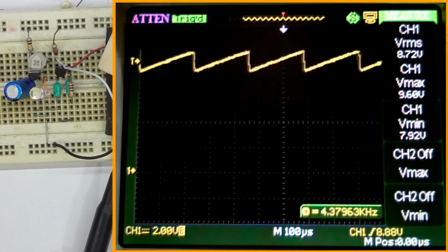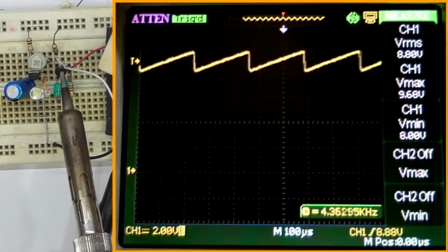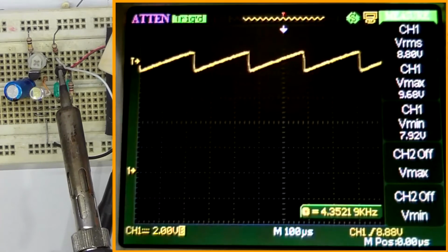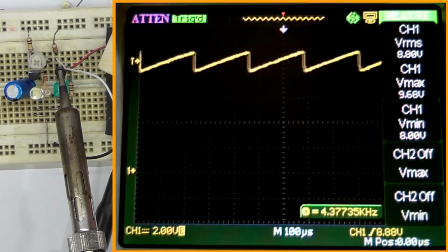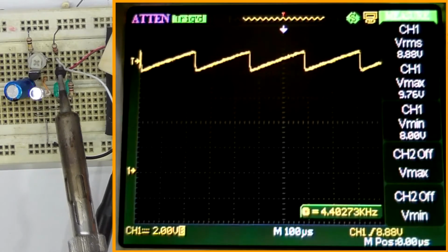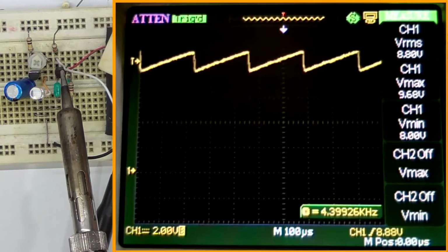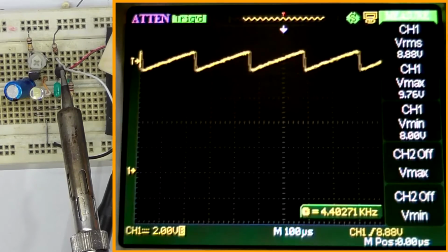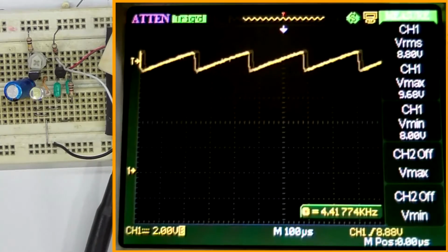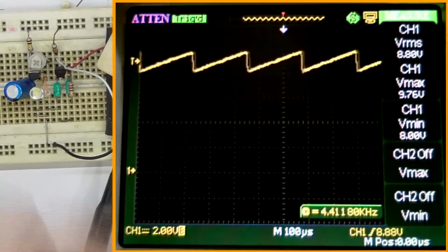And if I hit it with my soldering iron, which is set on its lowest range, about 150 degrees Celsius, just drop that on the top, not the most appropriate point to put it, but that'll do. Is it coming up or not? A better way: use some hot air on it now.